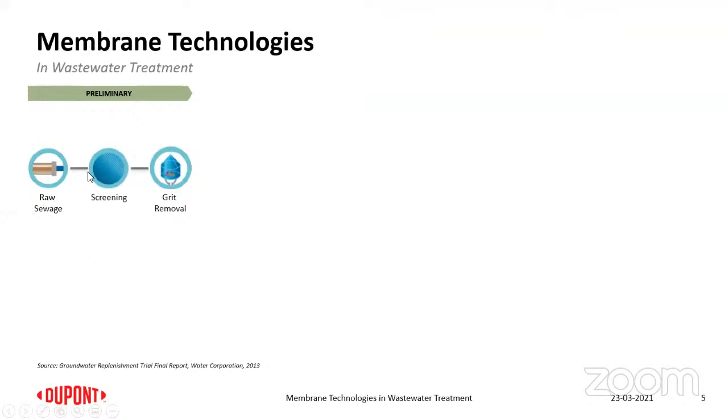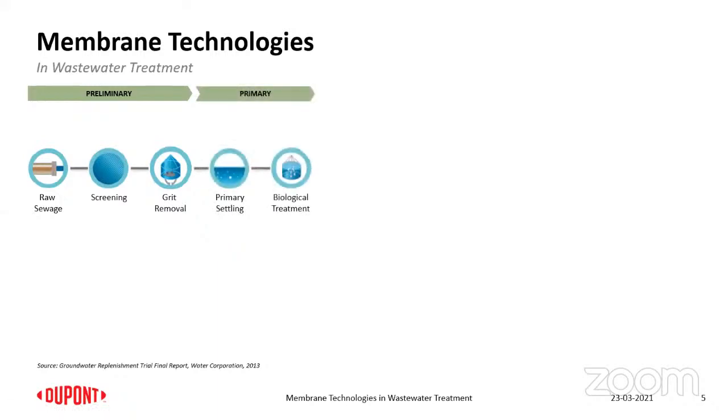Traditionally, raw sewage is screened. Immediately settling substances like grit are removed by fast settling. Then there is a primary biological treatment, wherein primary settling and the biological treatment, in a suspended form or an attached form, is done. It could be conventional activated sludge processes. It used to be aeration, surface or diffused aeration, and prior to discharge, it is subject to secondary settling, and it was discharged into the oceans. I would not necessarily say it's ocean.